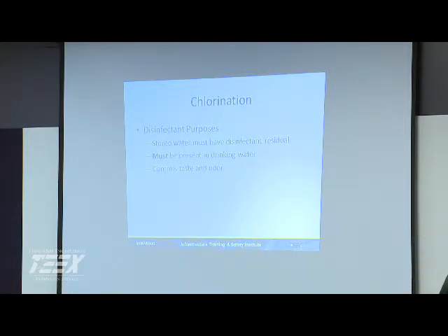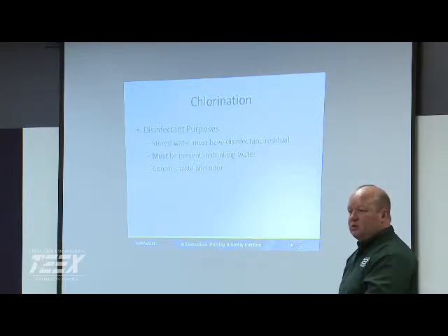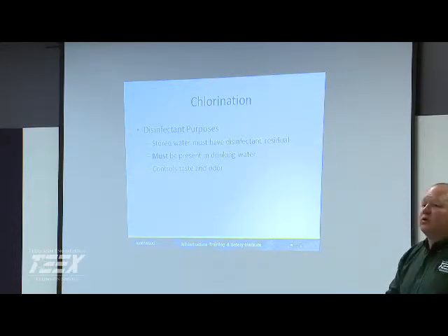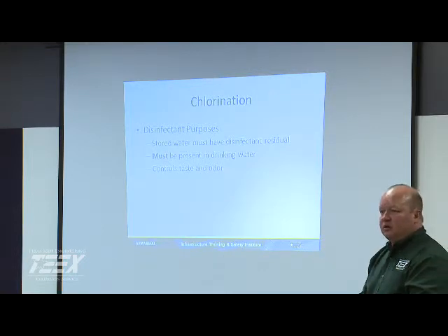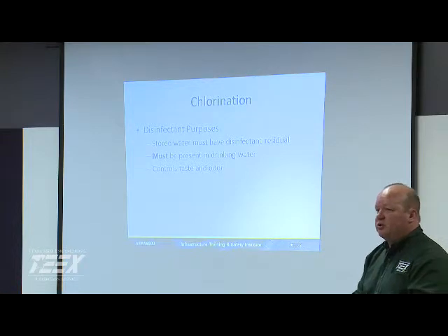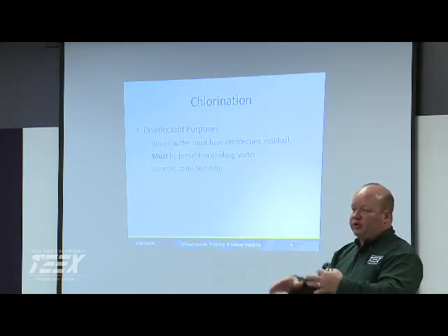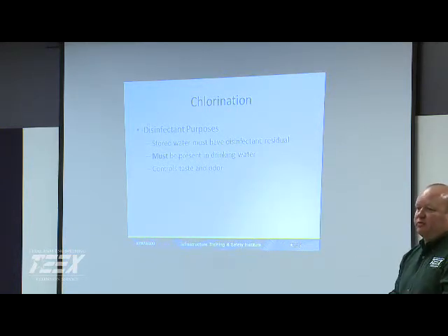One of the good things about chlorination, I don't know if y'all ever have taste and odor issues coming off the lake. You have lake turnover, you gotta worry about. We have lake turnover. We had a bad problem this year with it, but that's probably the worst I've ever seen. Are you de-stratifying at your intakes? We pre-treat with potassium. Okay, are you aerating anything right there? Because there are some mixing devices, or aeration on your intake, that'll help de-stratify that water, freshen it up before it comes in.